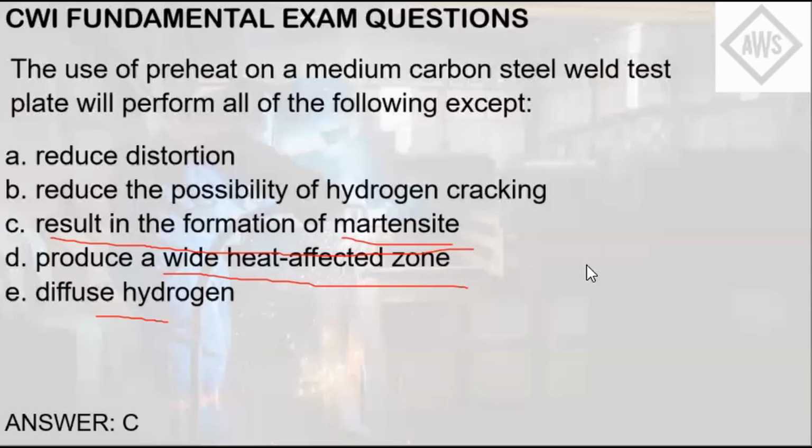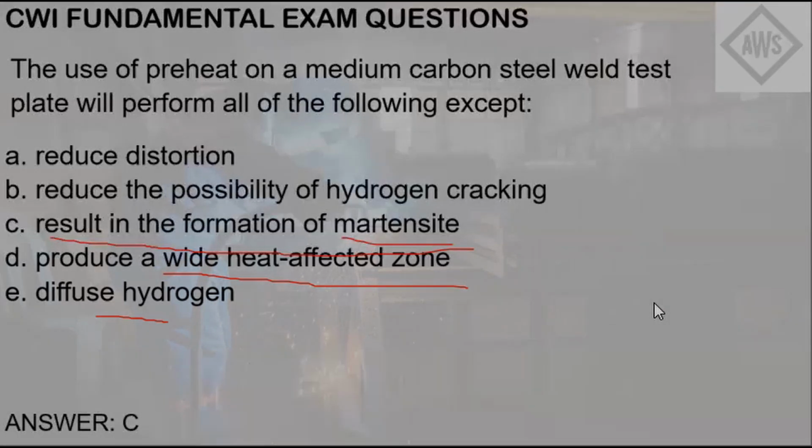Martensite makes the metal more brittle because it results in a coarser grain structure when you subject the material to a rapid cooling phase after heating or after welding it. If you see the coarse grain structure produced by martensite in a microscope, it resembles broken glass. So it is somewhat synonymous with the metal being brittle.